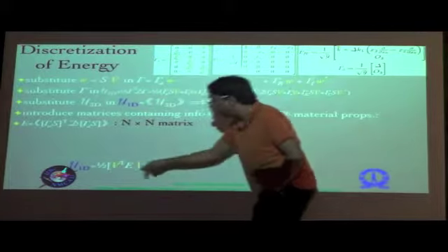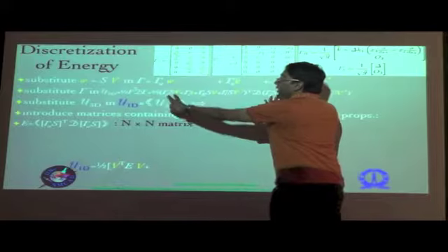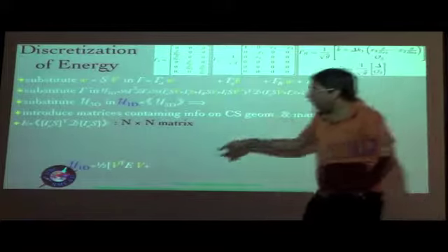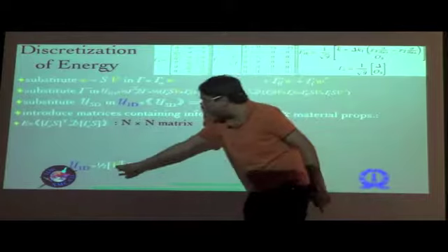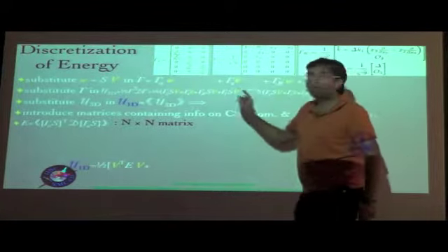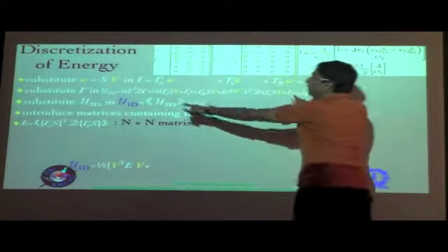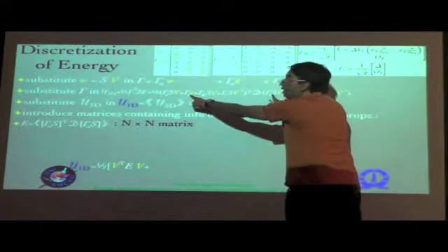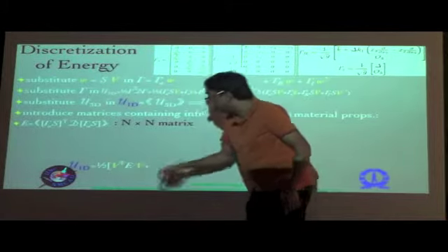The first term that you will have in U1D is basically by multiplying the first terms in both of these sides, which is basically gamma A SV and gamma A SV on both these sides. And that's when you multiply, you see that the unknown quantity basically is V. So it's basically V transpose EV, and that half would still remain because there's only one such product, whereas the cross products will be two. For example, if you multiply this with this, you can have one term like this, and similarly another term like this, which would have the same quantities, and therefore the two will cancel with the half. But here it doesn't, because they are both of the same quantity.